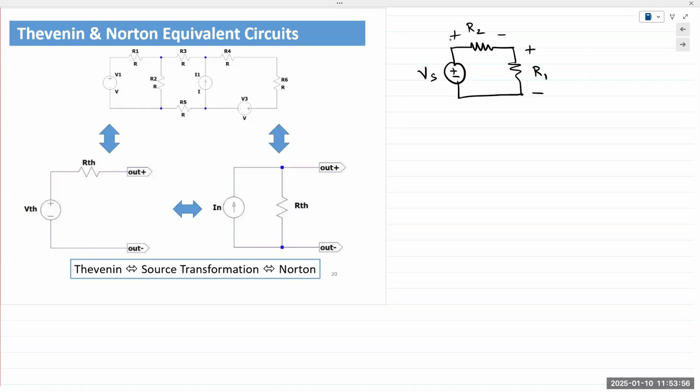So Thevenin and Norton theorems, they were postulated in the late 1800s by a French telegraph engineer known as Leon Charles Thevenin. And what he postulated was if you take a linear circuit, a large linear circuit comprised of sources, dependent sources with linear components, you could describe everything in that circuit with one single voltage source. Doesn't matter how many sources it had, but you could describe everything with one single voltage source in series with one single resistance. That's it. That's Thevenin theorem.